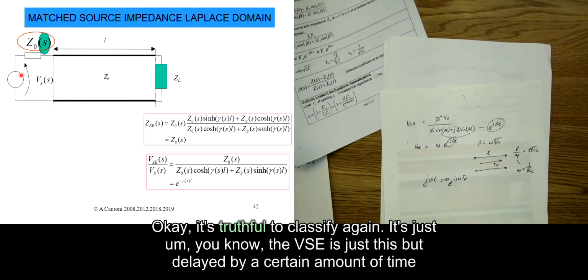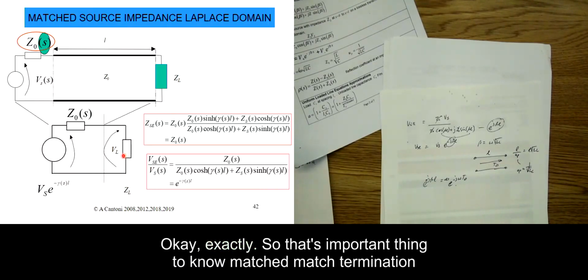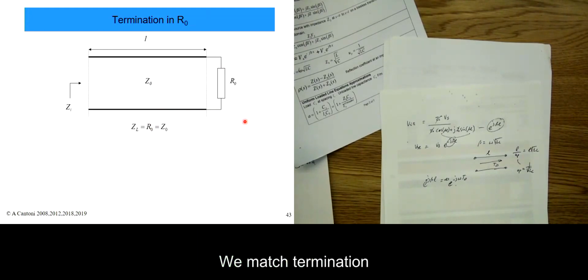It's true for the Laplace domain again. The source V_S is just this, but delayed by a certain amount of time. Okay, is that clear? So that's an important thing to know, matched termination. So we can also terminate the line in, say we've got a lossless line, then Z0 is equal to some R0, and we're going to put the load equal to R0. So now we've got matched termination, not matched source, but matched termination.